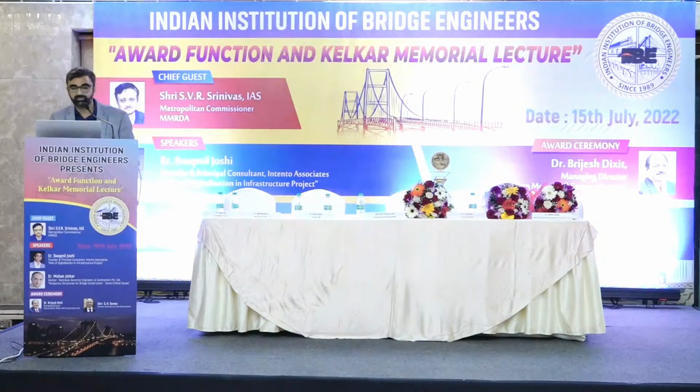the BIM concept initially. Post that, we now have various codes in place which can be used for naming conventions, asset tagging, or the BIM level of detailing. These are codes being used across the industry now, where PAS is a publicly available standard, and now we have BS codes, EN ISO 19650, which is widely used in various contracts. So it is now more structured.